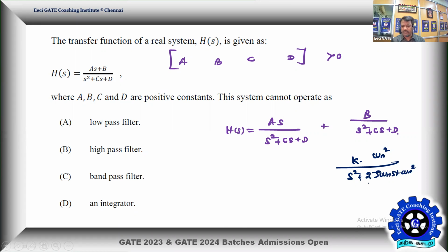If you make it a filter, then you can replace 2ζ by 1/Q, because Q is equal to 1/(2ζ), where Q is the frequency selectiveness of the filter. So you can represent the system in terms of damping, usually for time domain response, and Q, usually for the frequency domain. Since you are familiar with the damping based second order, that is a function known as a second order low pass function. So this term is a low pass function, and that's why you're comparing with the standard models.